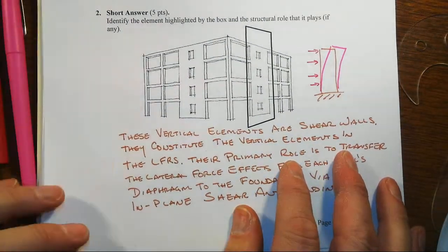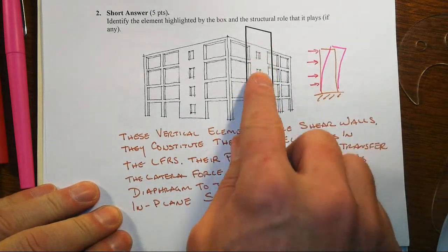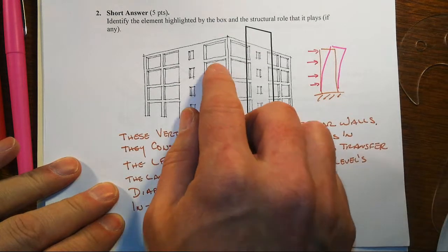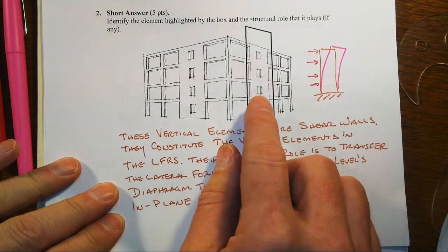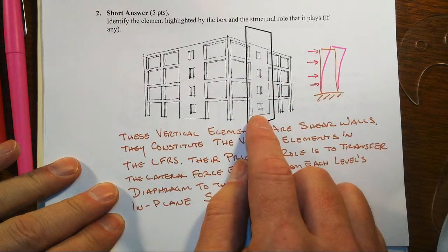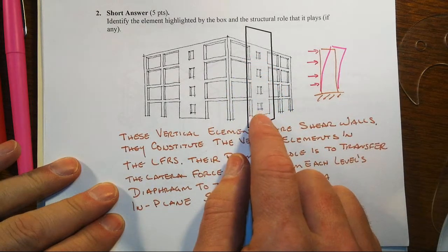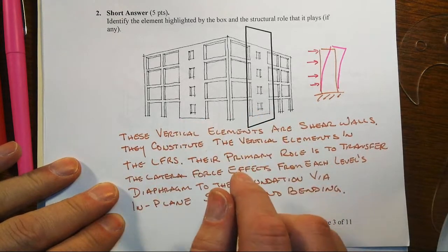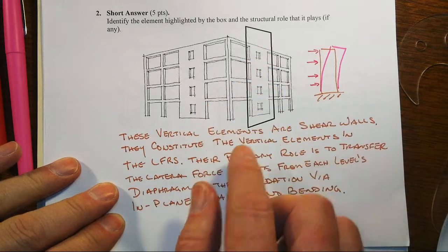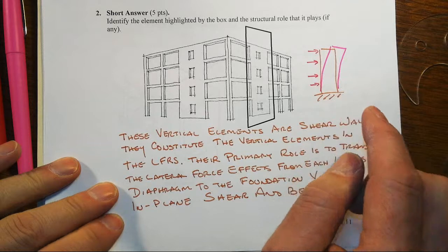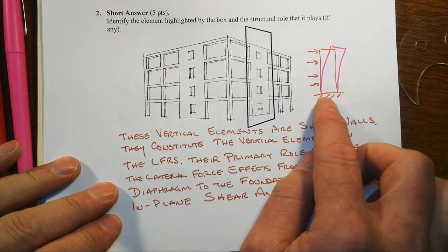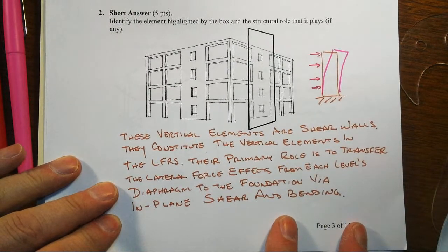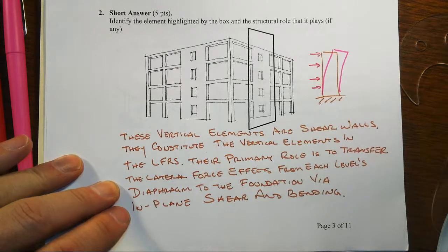The next one is about identifying what turns out to be these shear walls. Now, certainly we don't have any diagonally braced frames in here. These open panels tell us that we do have some sort of a wall system. We've got these openings in the wall system, and shear walls are so much stiffer than, say, these moment frames that anytime you have them, the building is going to be dominated by that kind of behavior. Right, so this thing is a shear wall. It's the vertical element of the lateral force resisting system. That shear wall will respond to the lateral loads that get transferred to it by the diaphragms through bending and shear deformation behavior.